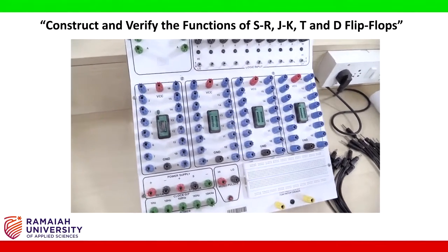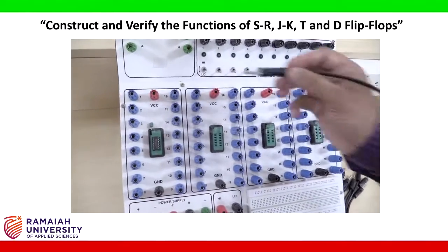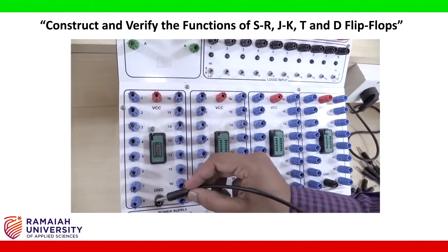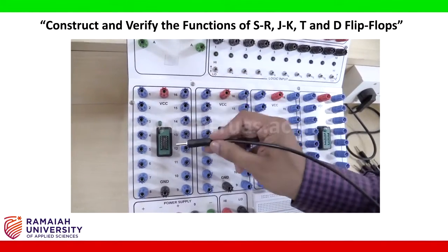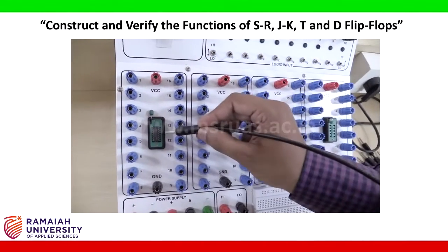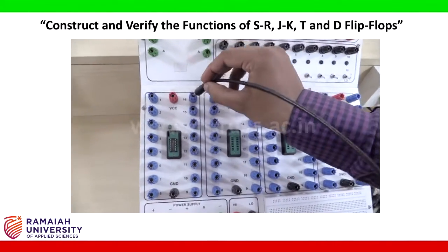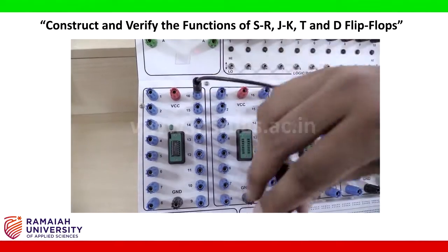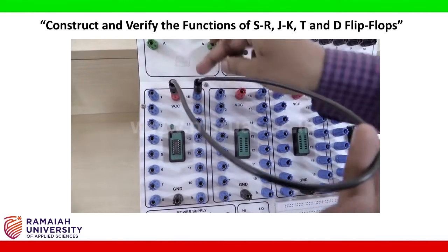Before connecting the circuit, make sure you are giving VCC and ground. This is to give the power supply to the IC. If you connect VCC and ground, it will give 5 volt DC power supply to the IC. Therefore I am connecting VCC to pin number 14.